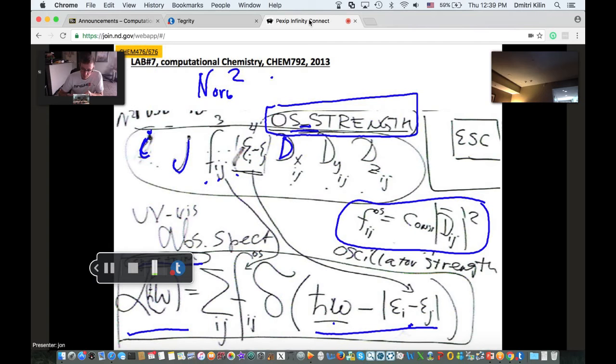And so the way that the script will put this out is in terms of that oscillator strength, so that the highest, most probable transitions are listed first. And then you'll see the energy of transition, or the orbital energy difference, in the next column, followed by the directional axis coordinates of x, y, and z for the transition.